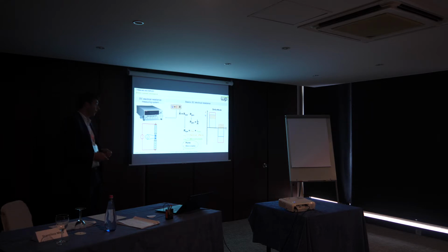The delta mode is to apply an alternating current once and measure the voltage, because the specific resistance depends on thermoelectrical effects, which depend on the polarity, so you can eliminate this.